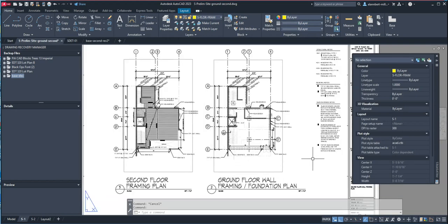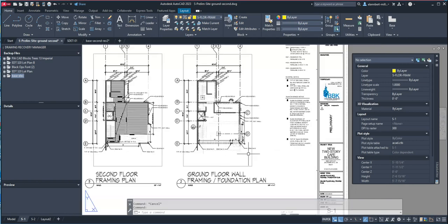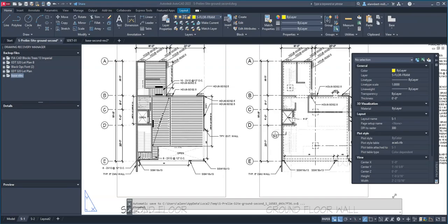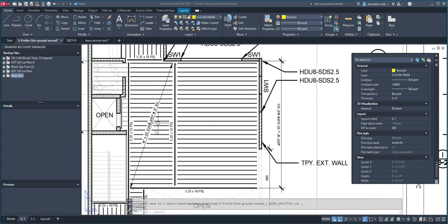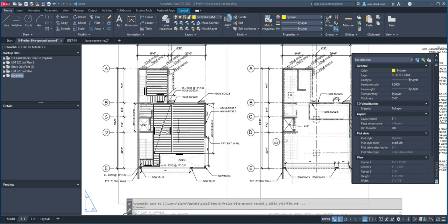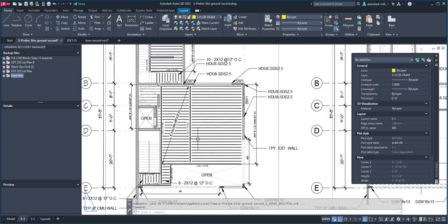We just have to add some notes here about the floor framing. So there, 3, 5, 7, 8. All right, so there's a lot more information that needs to be put here, including like connections and blocking. And the engineer is putting all that information because he is telling the contractor how to build this thing solid and sound. And if the information is not correct, then the contractor will have to clarify that.